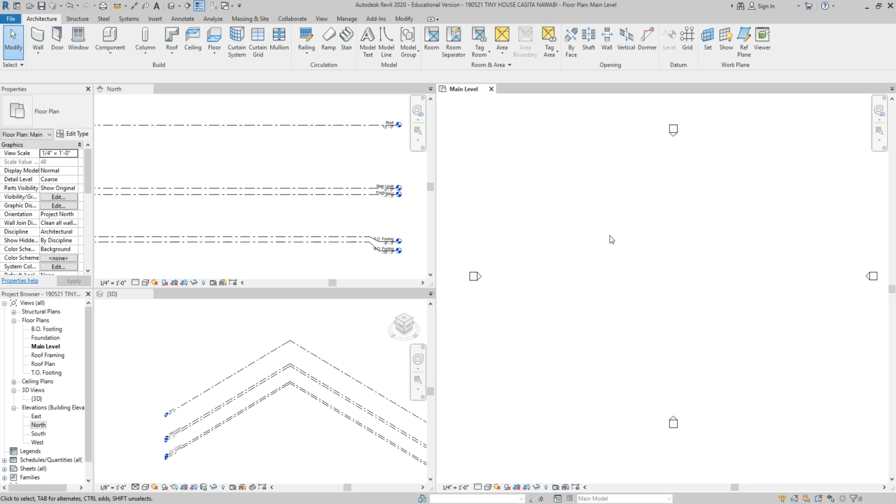So here, we're going to define some wall types that we'll be building in Revit. So this is going to be my wall type 1. This will be my wall type 2, and this will be my wall type 3. And we're going to define each one of those because remember, in BIM modeling, it doesn't have to be a generic wall. We can start with the generic wall and then add information later, but we have most of that information now, so it doesn't have to be generic. We can actually start with a pretty detailed wall.